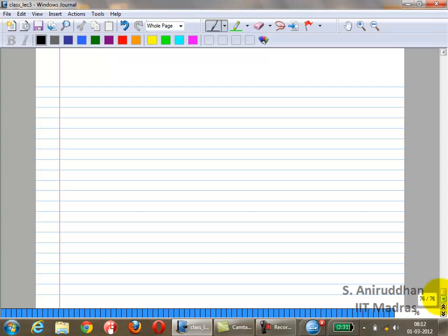Okay, so far we have been looking at single stage op amps. Even though the folded cascode looks like a two stage, it really is a single stage, because you have just converted a normal cascode to a folded cascode. So really there is no big difference. You have still tried to keep the fact that the output pole is the dominant pole, right? That's what you have tried to do so far. The other topology we looked at, maybe a couple of weeks ago, was the two-stage op-amp.